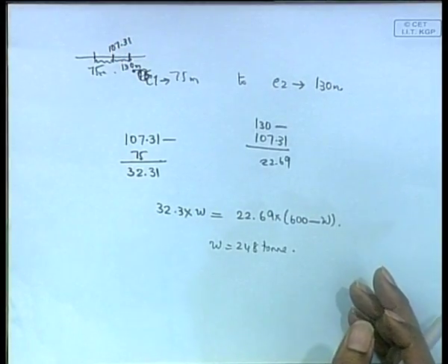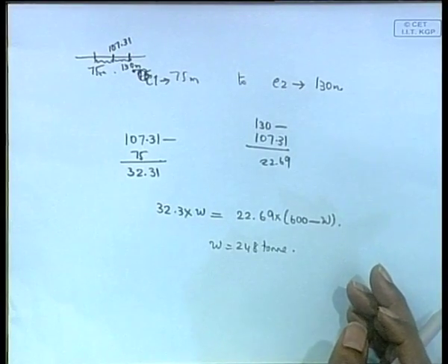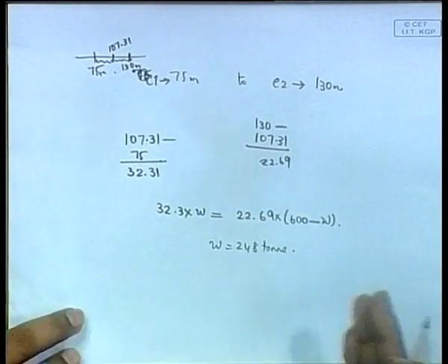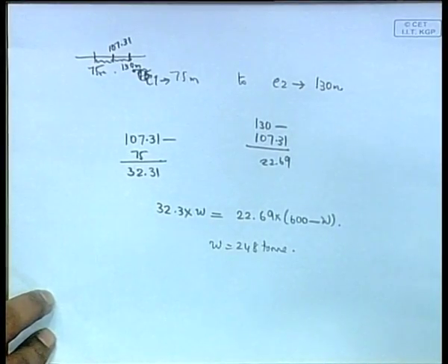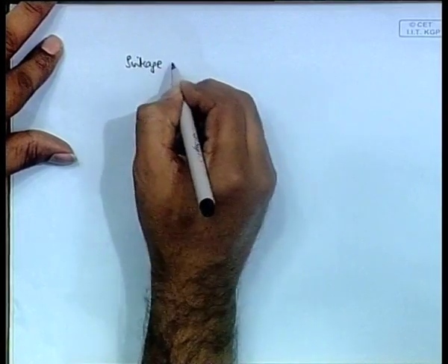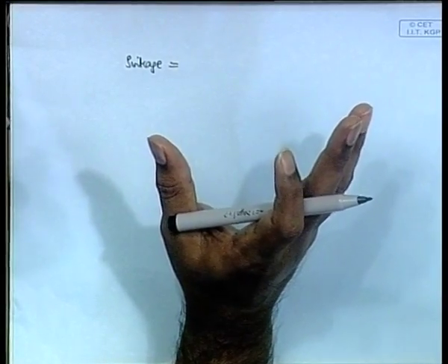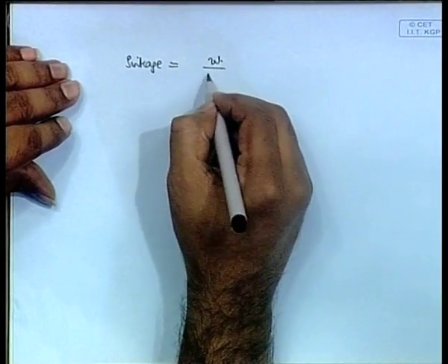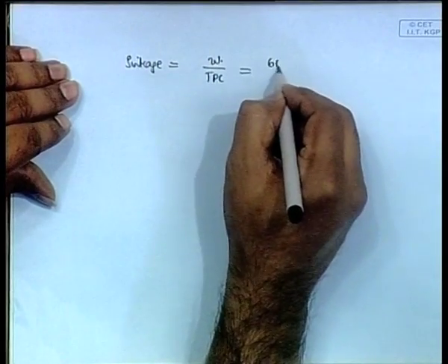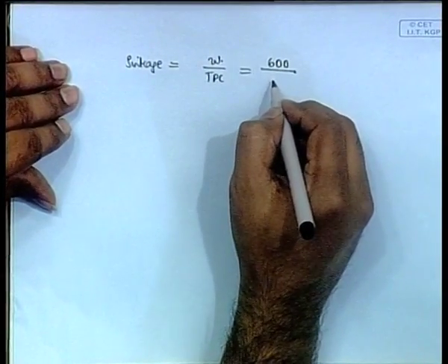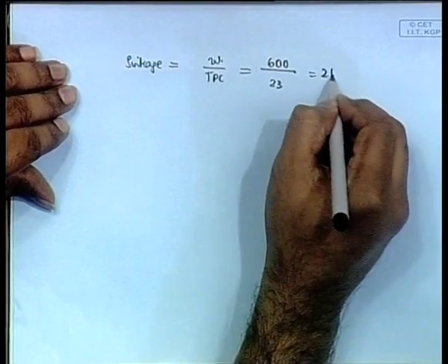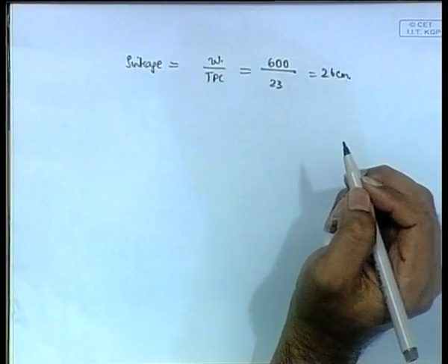Then this is the main part of the problem. Of course, you are also asked to find, once this weight is added in this fashion, what is your final position of draft. That is the same thing we have done many times. First you find the sinkage. So, here we are adding some weight at one point and another point. Total weight added, this is very straightforward. You are told that the weight added is 600 tons, which gives 26 centimeter. So, this much of sinkage you get.